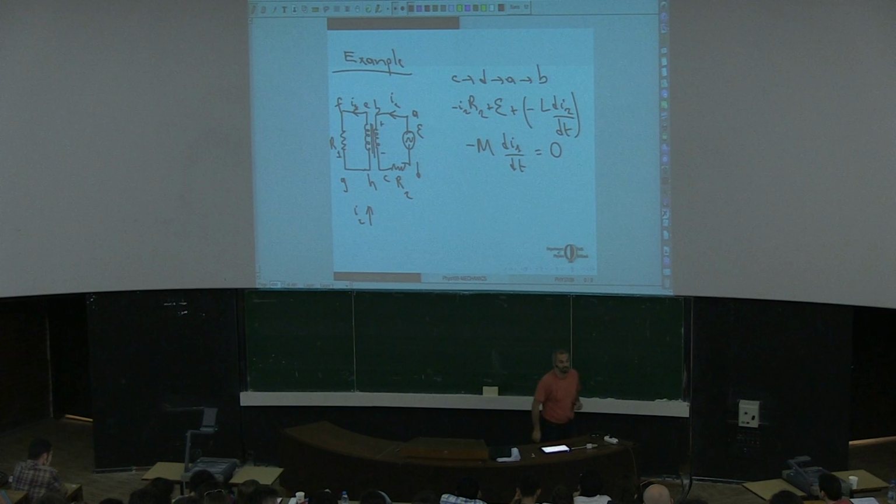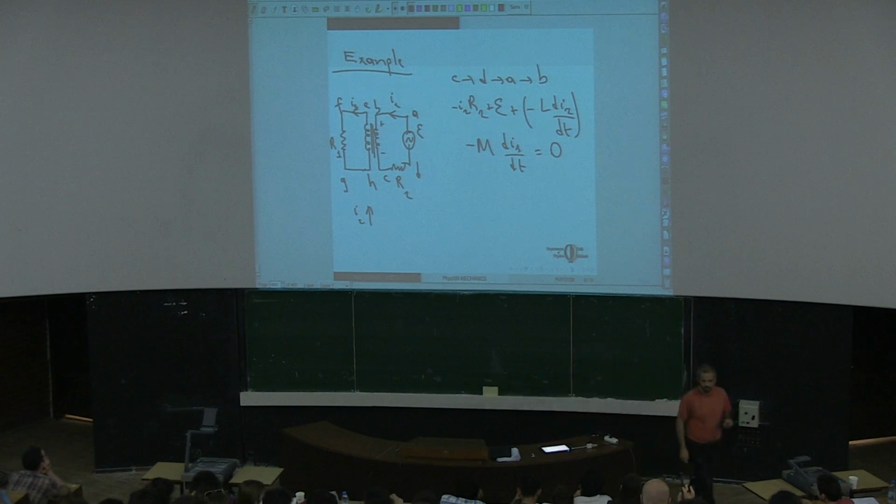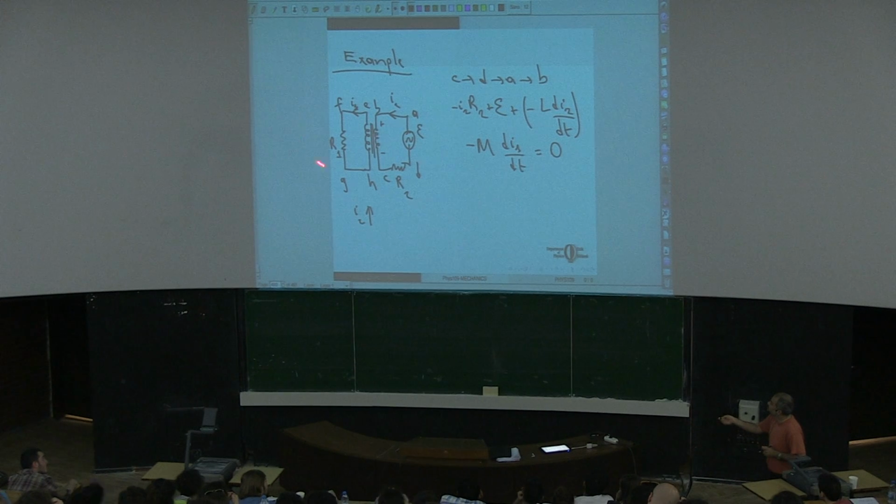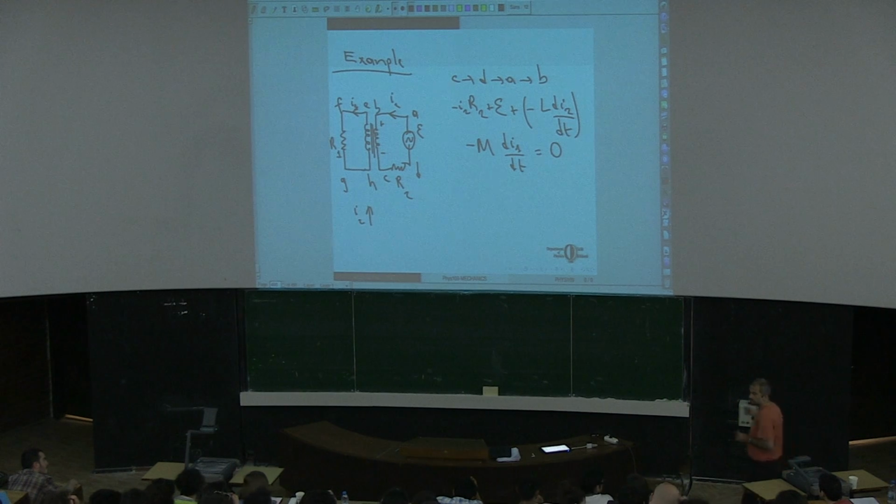Okay, this is one of our equations. Now, why is this minus? It should be a given information. So if I1 is increasing in this direction, then it will try to create a current in this direction in the other circuit. That depends on how this thing over here is wired. So that's an information that should have been given.